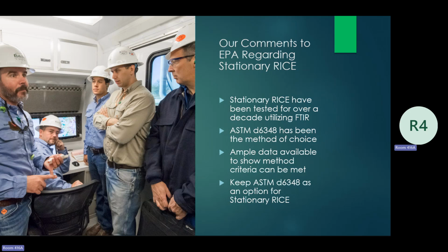What EPA has said also is that while they're going to disallow ASTM D6348 for right now, they will allow it if there is a revision done to the ASTM method. I can tell you, as a former committee member to that revision of that method, that committee has disbanded. There will be no updated ASTM method that will come out anytime soon.